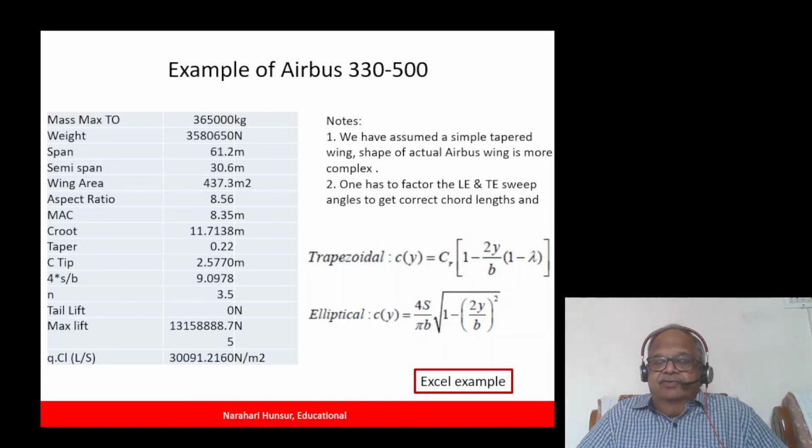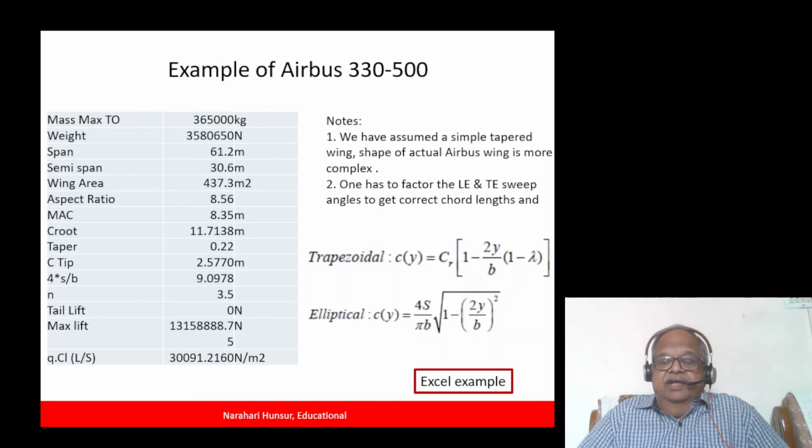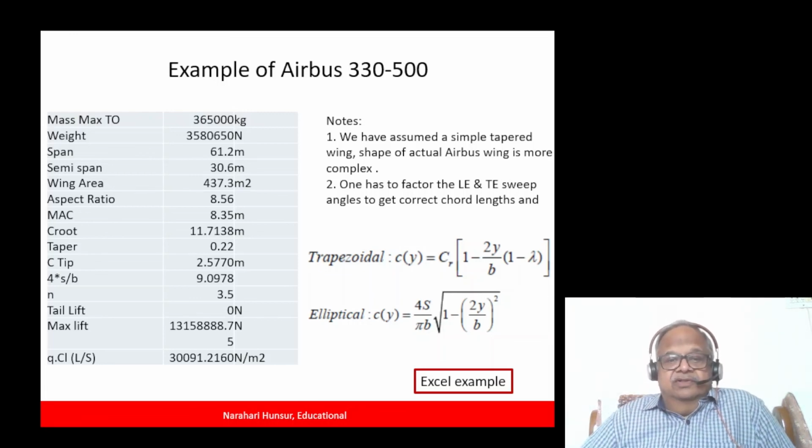Similarly, you have shear force diagram, and to check how accurate or whether there has been any errors, you do a quick sanity check. Now we have computed the strip areas of all the strips, right? So, you can look at adding all the strip areas as to what's the strip area you come out with. And that shows up as 218.65, and is almost exactly the same as what you started off with.